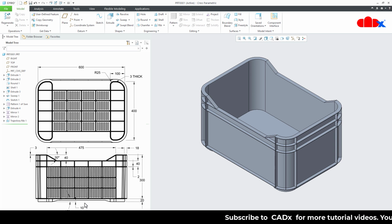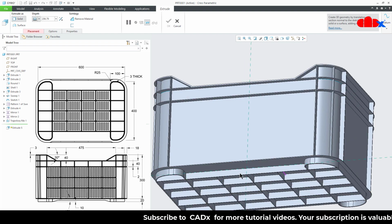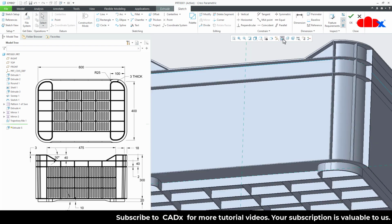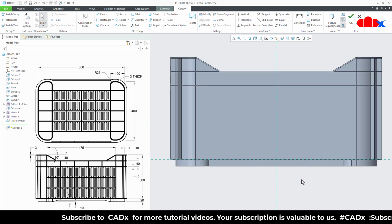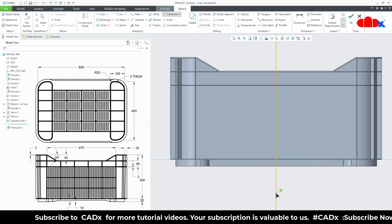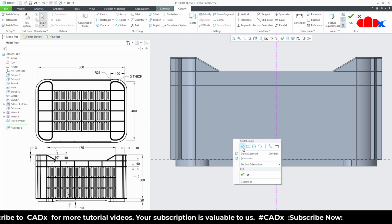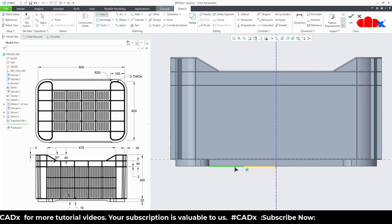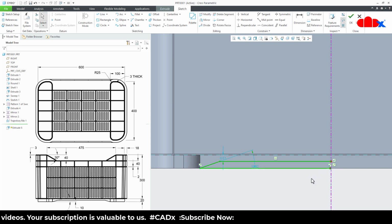Now I have this cut feature. So go to extrude, select this face, normal. Now here you add a center line somewhere here. Then draw a sketch. Start from here, go like this, then go like this, and then like this.